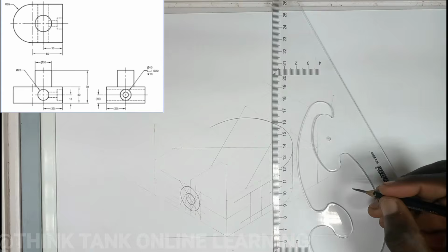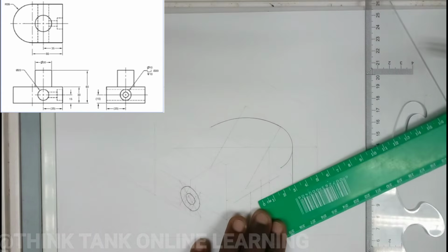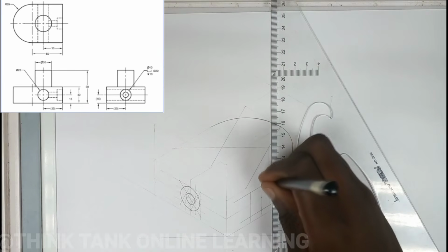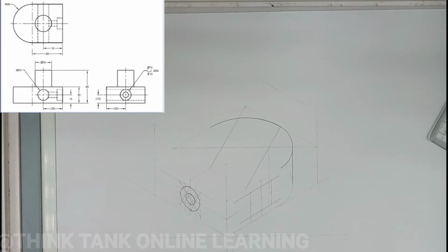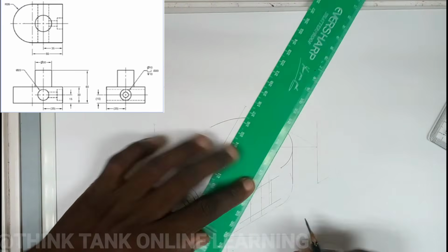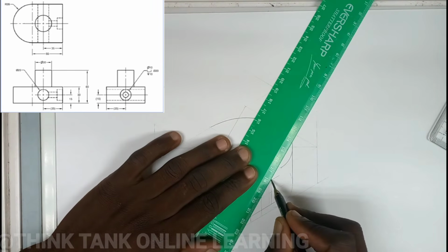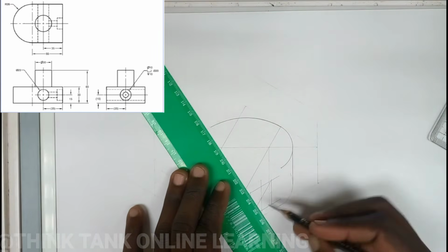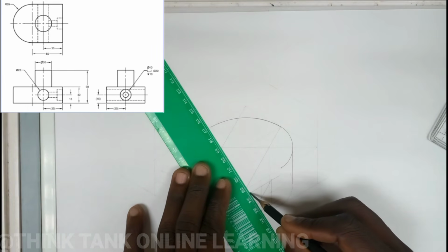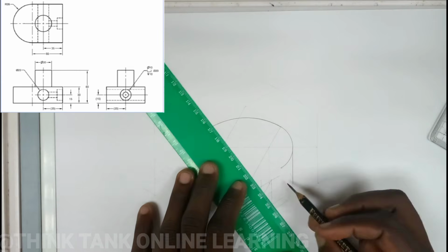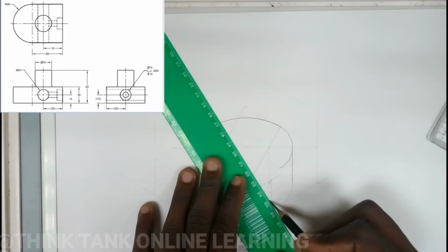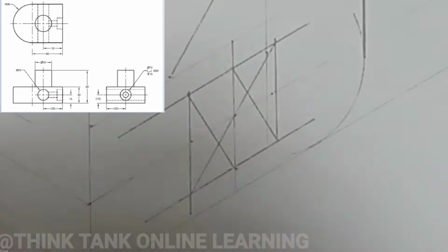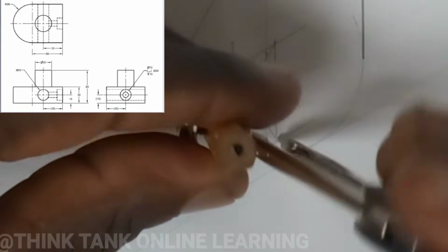Draw a square. Okay, repeat the same process. Join this diagonal and that diagonal, which is long. Join this point and this point. Join this point and this point. Okay, and now you have all the center points. You can draw a circle.